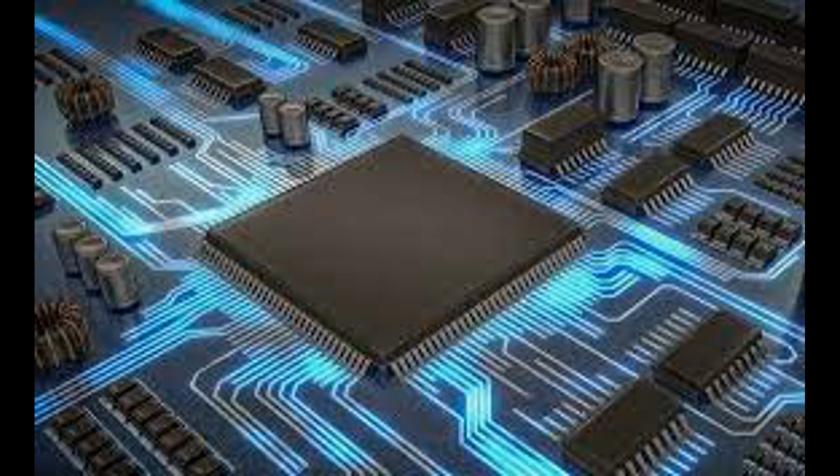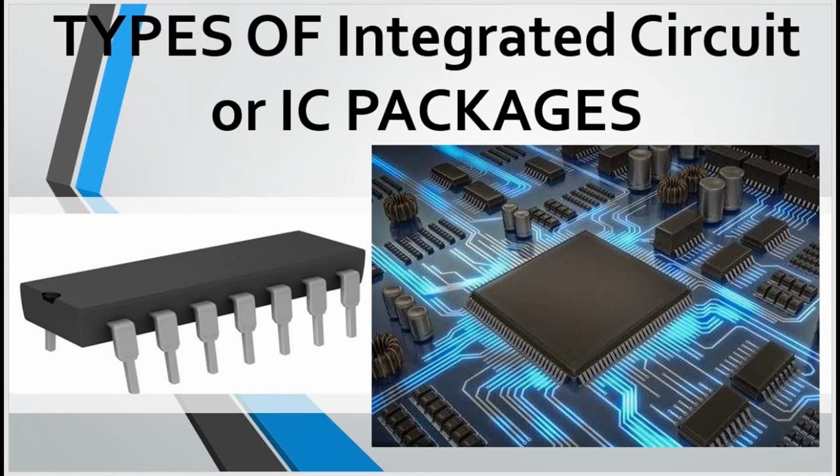Functionality. Different types of registers serve specific purposes. General-purpose registers, used for a wide range of data manipulation tasks, such as arithmetic, logic operations, and data movement. Program counter. PC stores the memory address of the next instruction to be executed. Stack pointer. SP keeps track of the top of the stack in a computer's memory. Instruction register. IR holds the current instruction being executed.